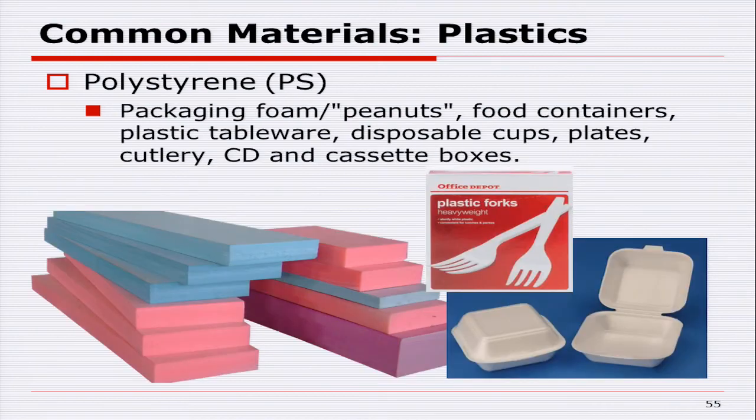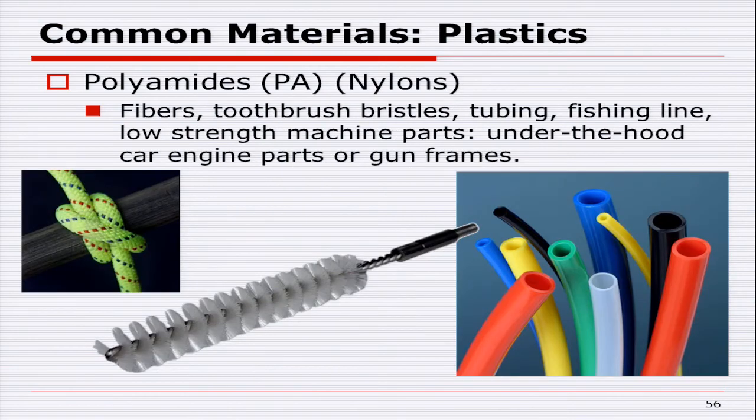Polystyrene, you probably know it as styrofoam. It was developed by Dow Chemical, and their trade name for it was styrofoam. But it can come in a couple different forms, either an extruded polystyrene, or what we call expanded polystyrene. Expanded polystyrene, we typically call the beadboard stuff. If you look at those coffee cups that look like they're made out of lots of little small beads pressed together, again, that's polystyrene. Only the beads were pushed and put into a form with the addition of steam. So they're put in there in a pretty warm state, and they consolidate and bond together.